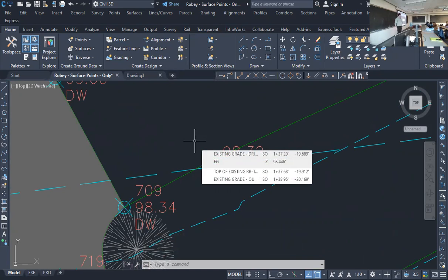Okay, Chris. Can we draw that over the ones we already have for a sidewalk? Yes, because the sidewalk should just be a two-dimensional line. It should not have elevation associated with it. Otherwise, if you wanted to hatch that sidewalk, the program's going to be like, what are you talking about? It needs a closed figure to create a hatch. So yes, you are going to draw right over the top of it. The other thing drawing it first is going to help you with is the curves, and I'm going to show you that right now.